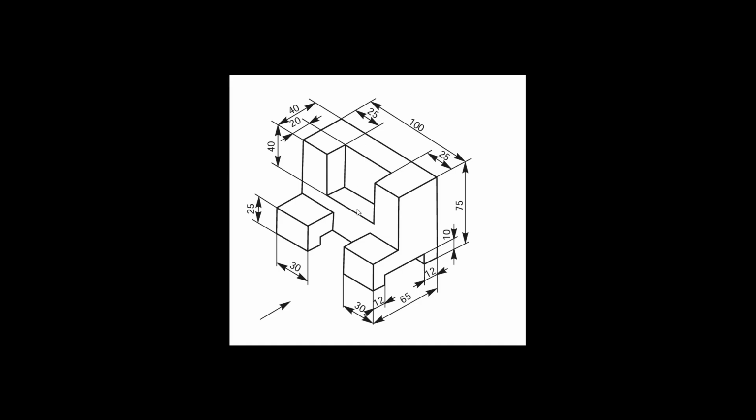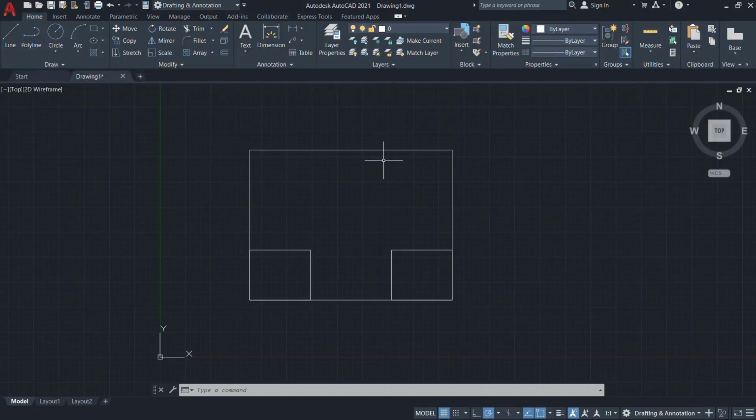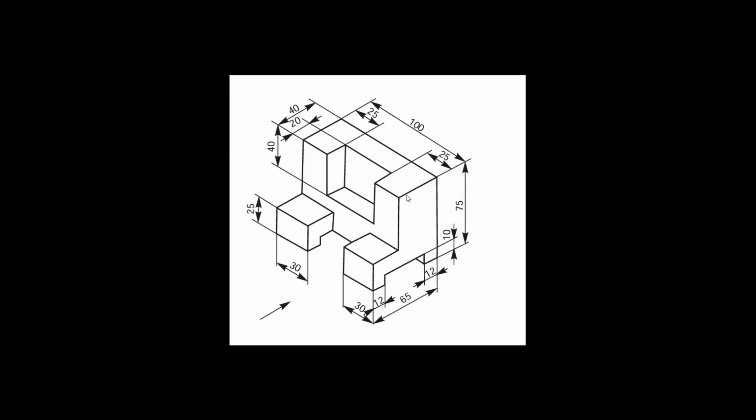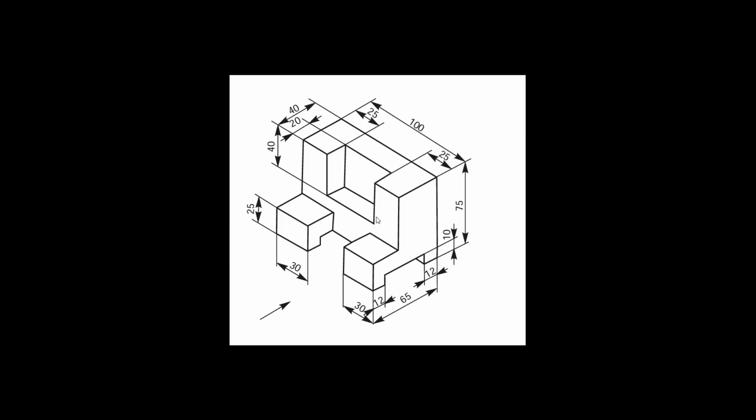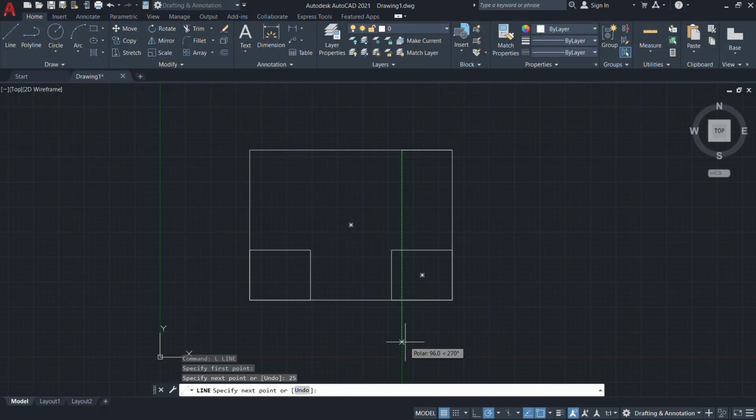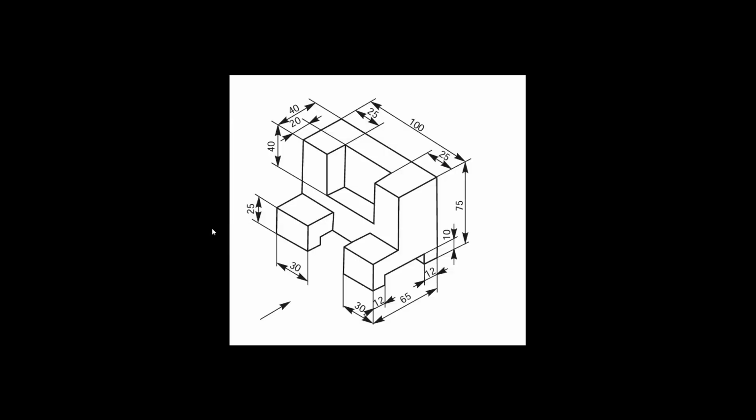Next, look at the top portions. There is another rectangular profile indicating the pocket portion. So instead of drawing a rectangle, first I choose a line profile, which needs to be offset from its particular position by 25 mm. So using a line, mention 25 mm horizontally, then draw one vertical line profile. What does it mean? 40 mm in the vertical direction. So once we specify, position the cursor, then mention 40 mm vertically.